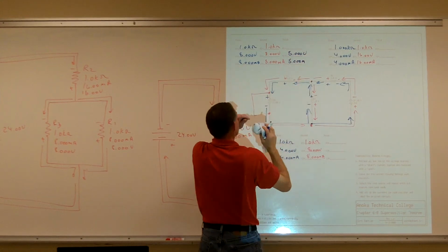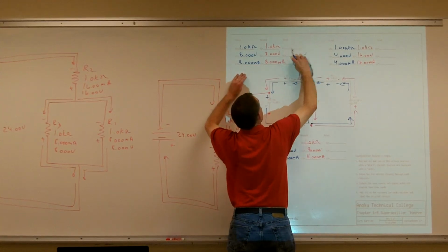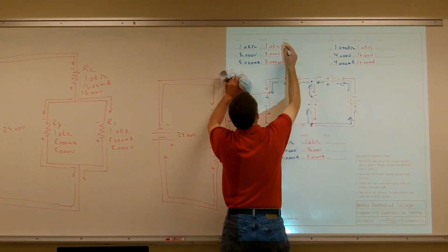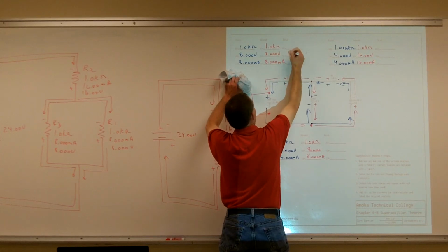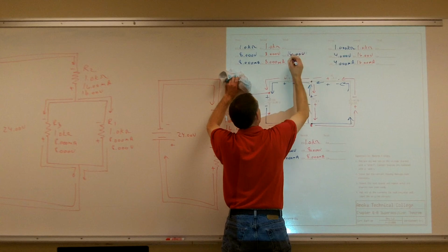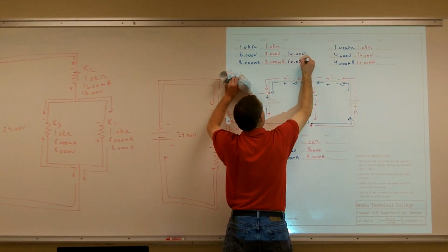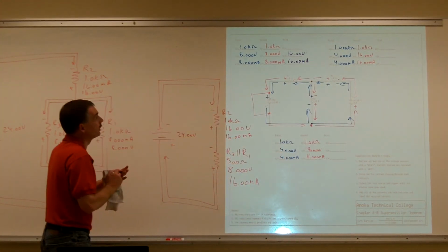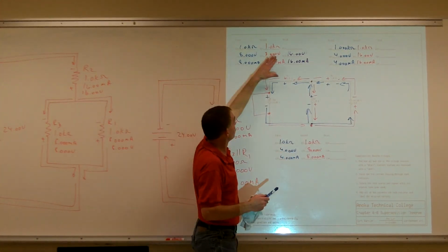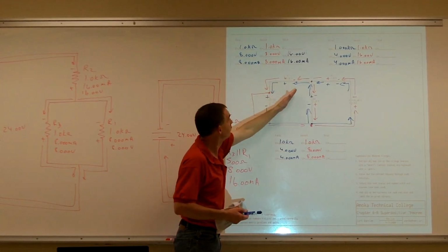So I'm going to have twice as much voltage and twice as much current: 16 volts being dropped across that one, and 16 milliamps of current. If the currents are both going in the same direction, I'm just going to add them up.